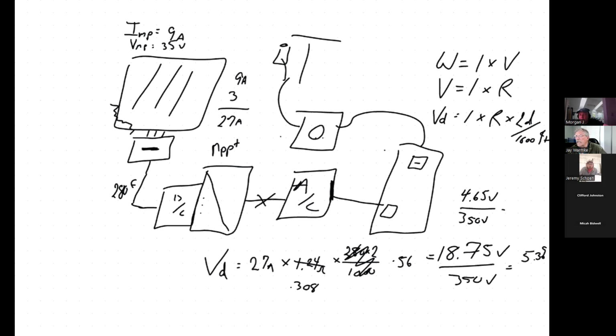And I can already see that's going to be about 1.5, right? Yeah, 1.33%. So that works, right? Problem is we just spent some money. Instead of 10-gauge wire, we just put in 4-gauge wire. So instead of spending about 20 cents a foot, we probably spent about $1 a foot times 280. So we spent another $500, something like that. Yeah, you do what you got to do.